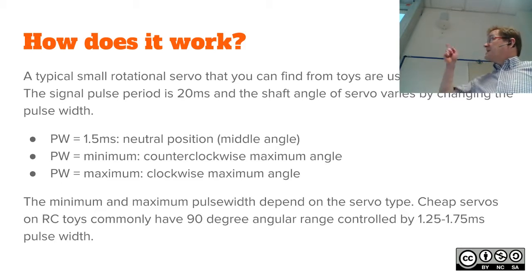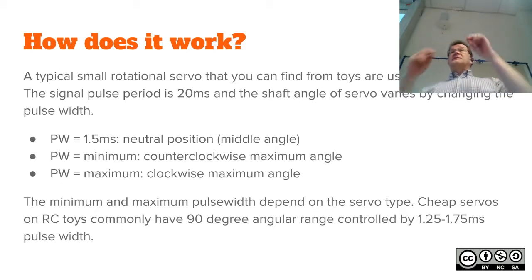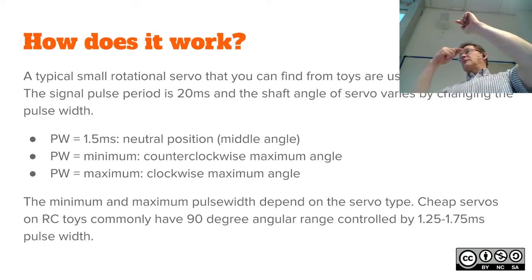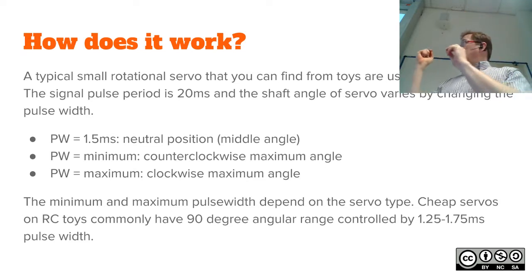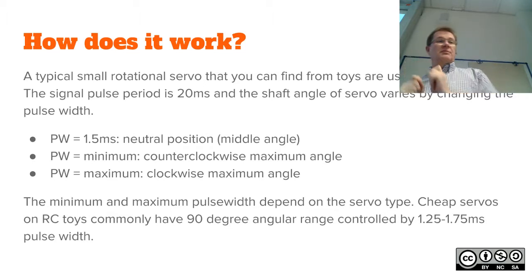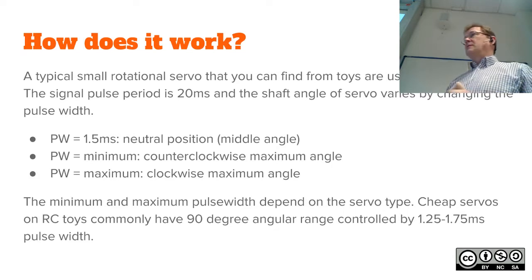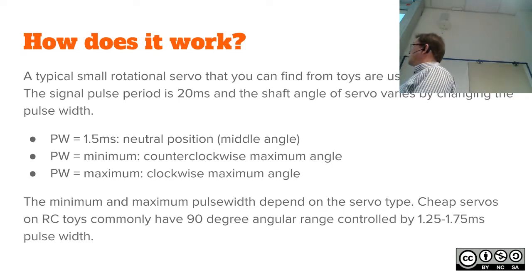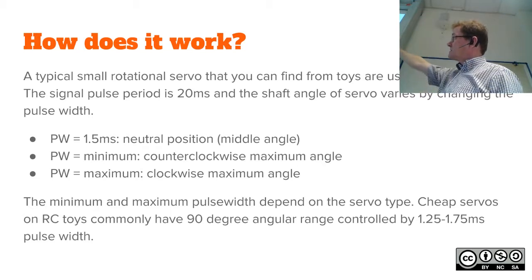The standard signal is very simple. You just have the power and ground signal, and then basically pulse width modulation is used there. Or actually, the duration of the on state defines the angle.